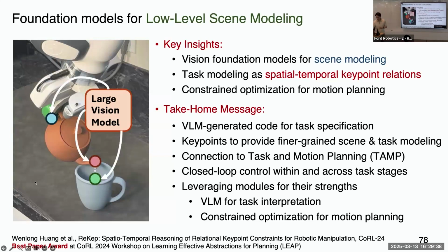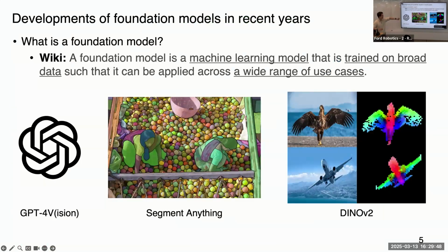That is a very good question. So for this specific case, what we are taking advantage of is this earlier work I showed here. It's called Dino, shown on the right. You can see the visualizations of the pixel-aligned features that give you very interesting and good semantic level descriptions about different parts of an object. So what we did was fuse this information from multiple cameras into a 3D unified space, and we do clustering over this visualized 3D space. If we do clustering, we actually can have key points over semantically meaningful parts of these environments.